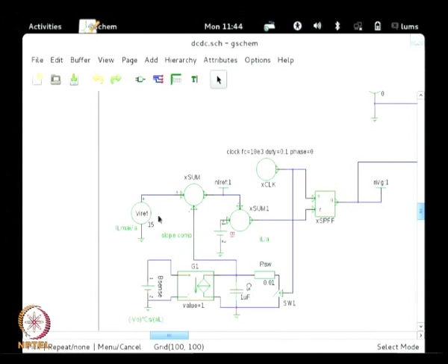So, you have a constant current reference here, and based on the slope of a current which is proportional to the negative slope of the inductor current, V naught by L, is fed through this current controlled source CCCS, and the current through this is used to charge up a capacitance.